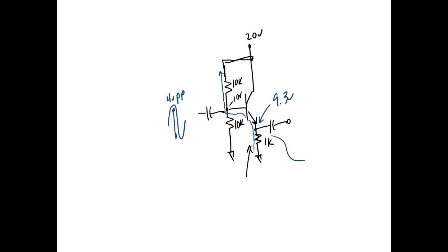So that means if I put 4 volts peak to peak on the input, I might be getting 3.9 volts peak to peak out, because the only voltage we lose is by RE prime. So we will never get exactly the same voltage on the emitter that's on the base. The emitter will be slightly less. But these guys right here have an AV equal to approximately 1. You can't get any voltage gain out of them.